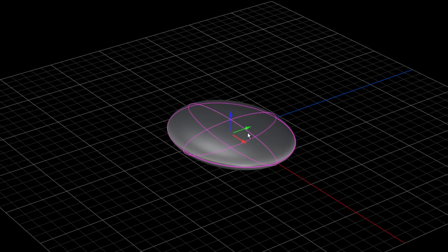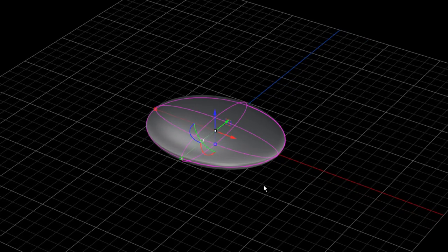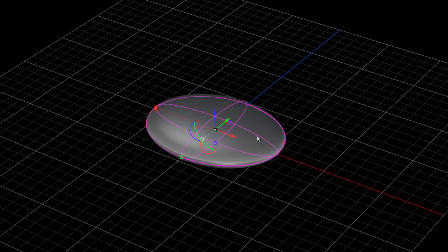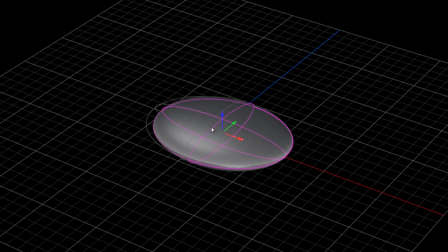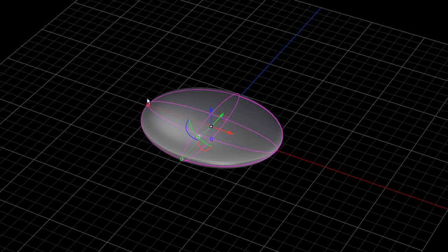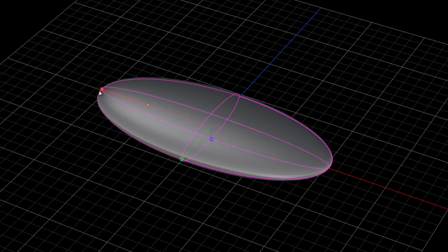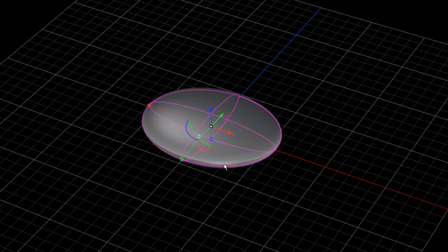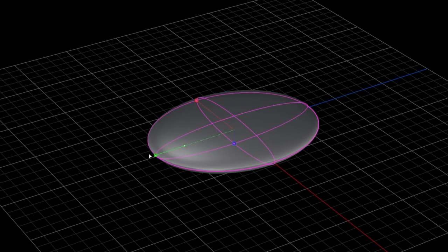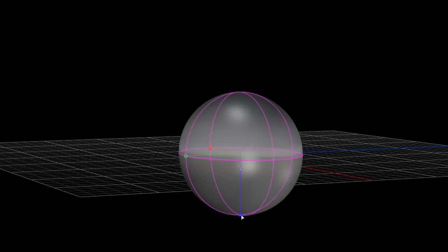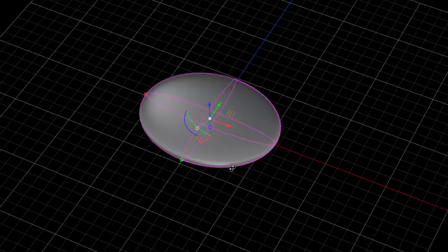If anyone has used our MSR controls or the T-spline HUD manipulators, you'll be very familiar with what is happening here with the Rhino Gumball. Right, so you can see, it allows for movement. We also have individual little spots right here for scale. As I click and drag on these, this would be a 1D scale. There'll be one running in the other direction, and then one vertically for scaling within the Z.